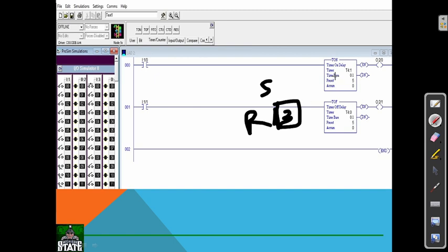Whereas in the on delay timer or off delay timer, once the power is cut, it won't hold the same minutes. Whereas the retentive timer won't return back to the previous time. It will stay stuck at that particular time, then start from the same time. That is the retentive timer.